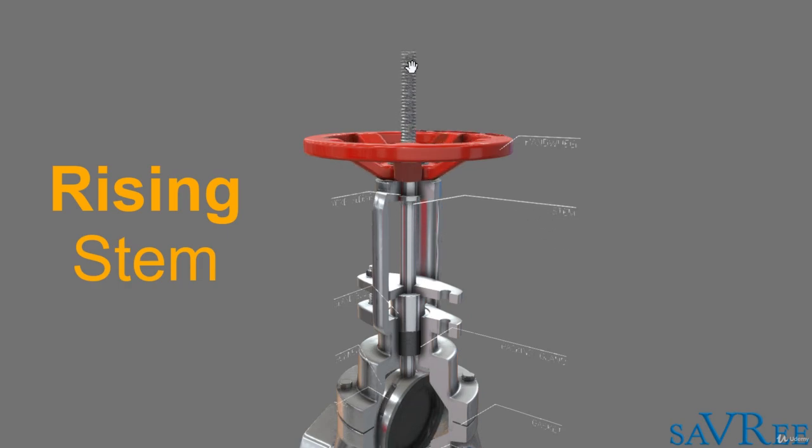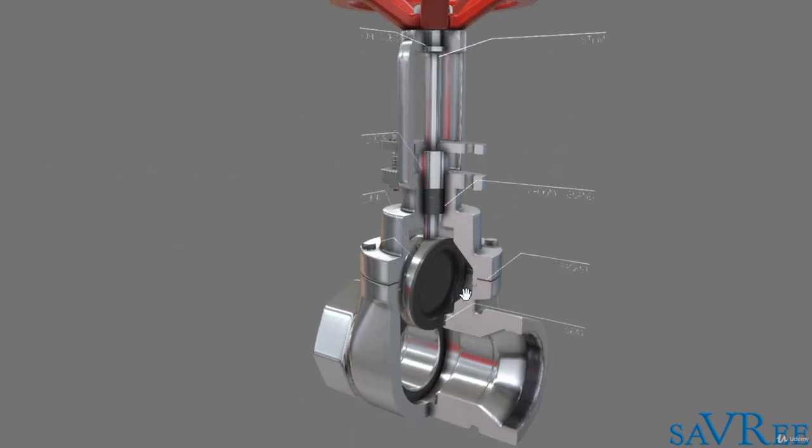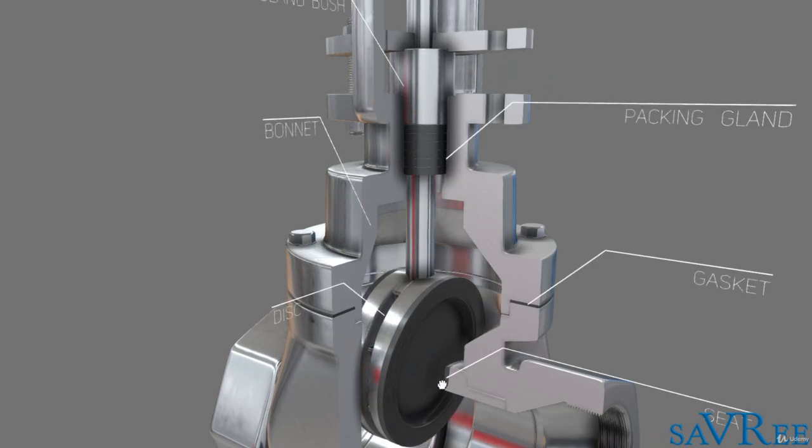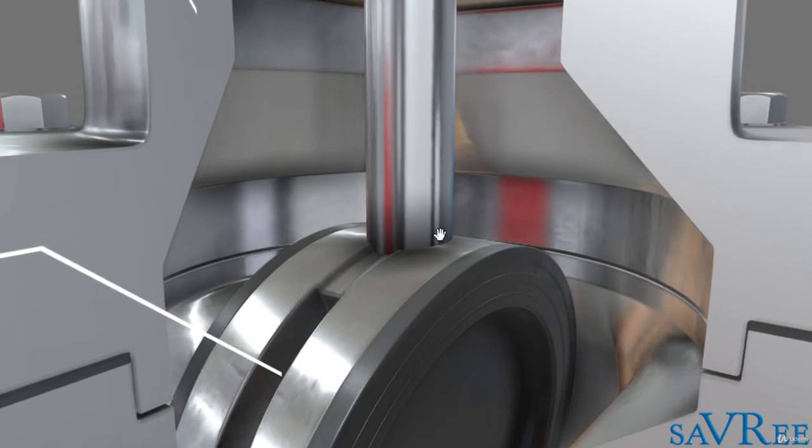It makes it really easy to see the position that the valve is in because the stem's just going to pop out of the top. In order to achieve this, what we've actually done is fix the stem to the disc. So the stem is connected to the disc. It is not going to move inside the disc or anything like that. It's totally fixed. And that means that as we rotate the handwheel, the stem is going to be pulled upwards and it's going to pull the disc up.